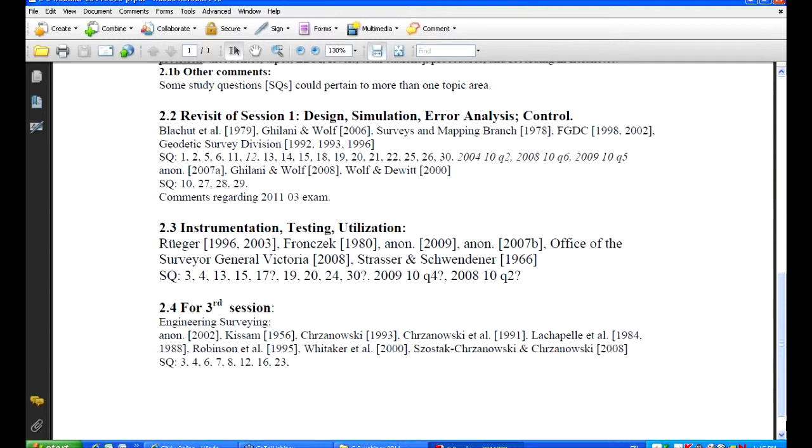So if we take simply a linear array of points, which can be created by mounting tribrachs onto tripods and lining them up, we can actually do a least squares estimation using all the possible distances. So for instance, if we had 6 points, we would have 15 possible distances. And the problem then is coming up with the observation equation that would relate these distances to the quantities that we don't know. And the quantities that we don't know are the additive constant and the coordinates along this linear baseline.